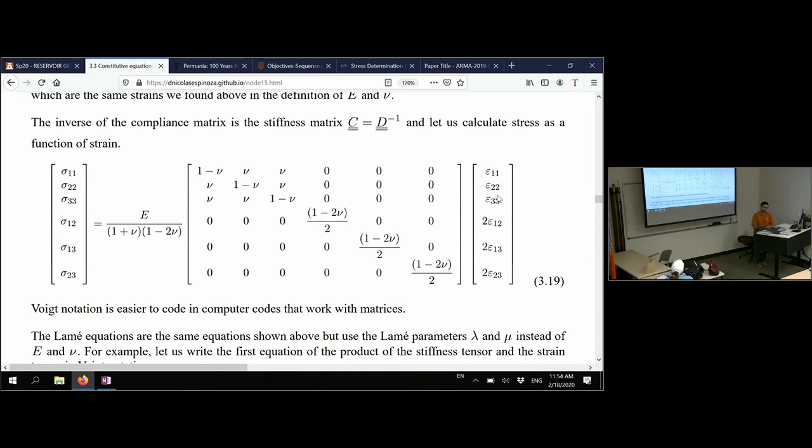And that's the case in which we have stresses that are compressing the rock horizontally, or you may be in a region in which there is lateral movement, in an extensional environment, and it's moving outwards. So in that case you will have a negative tectonic strain. But now these are not going to be zero. But still, you do the same thing. You calculate sigma 1, sigma 2, sigma 3 by multiplying rows times column, and you will get 3 equations.